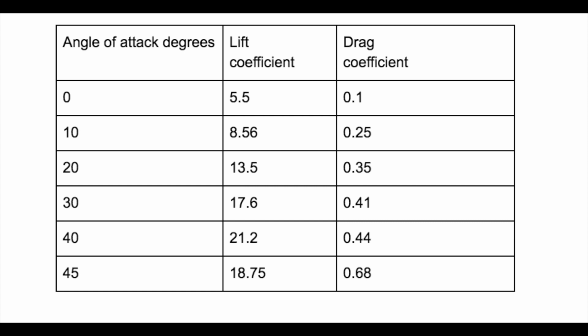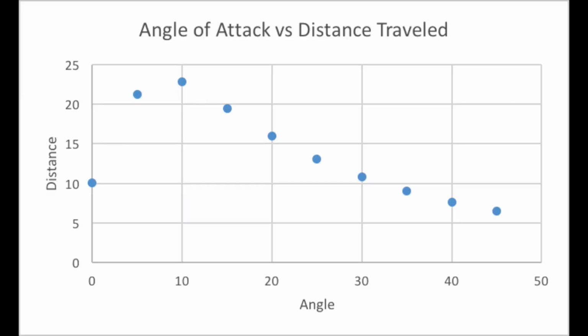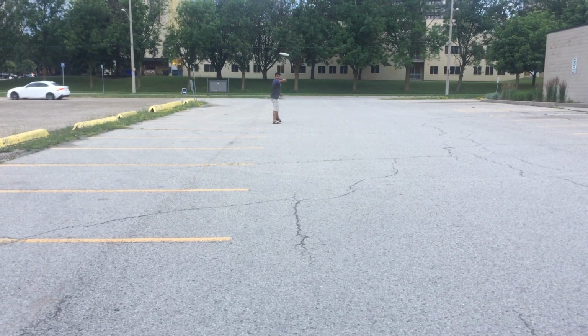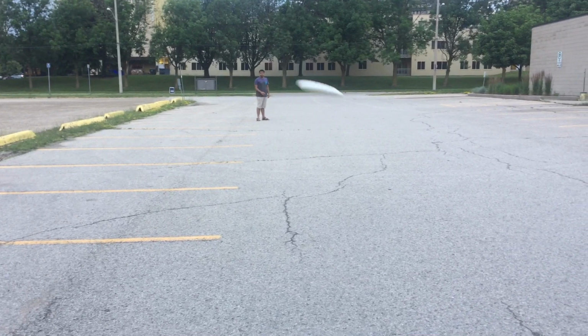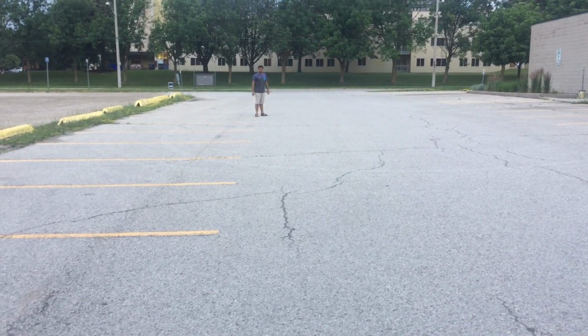The ANSYS simulation helps visualize the relation between the angle of the disc, the velocity, and the pressure of air flowing around it. These pressures provide the lift and drag forces, which change depending on the angle of attack. The relations between the angle of attack, drag, and lift are similar between the ANSYS simulations and the coefficients calculated using the equations in the MATLAB solver. Both of these methods demonstrated consistent frisbee behavior, which is also further validated by real-life data.